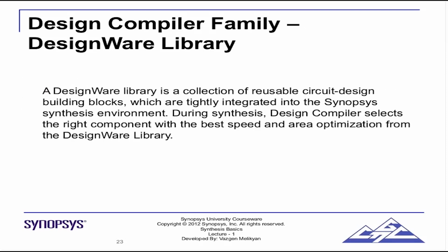There's a family of components called DesignWare. Now, recall that the process of translation converts the RTL into a GTECH netlist, into a generic Boolean netlist. The DesignWare library is a collection of reusable circuit design building blocks which are tightly integrated into the Synopsys synthesis environment.